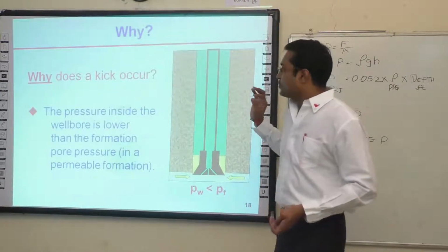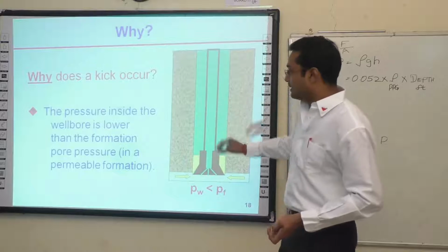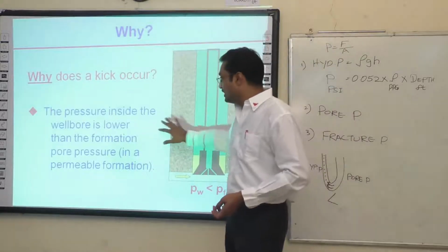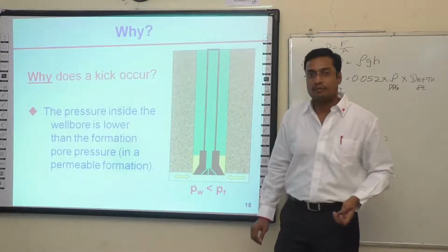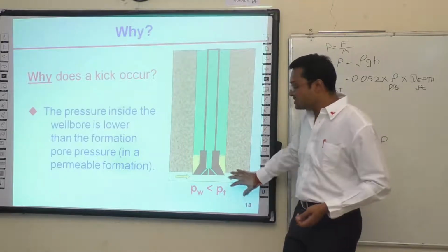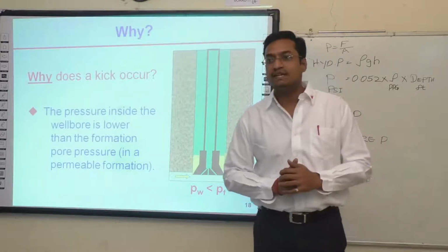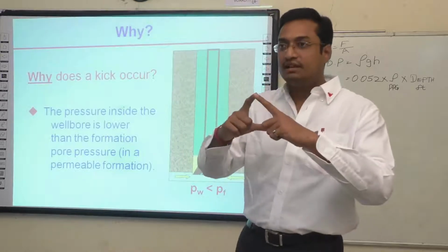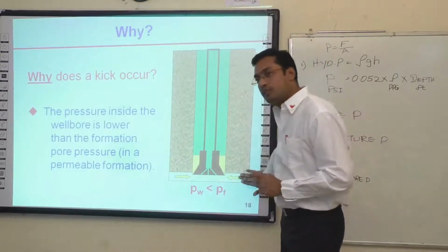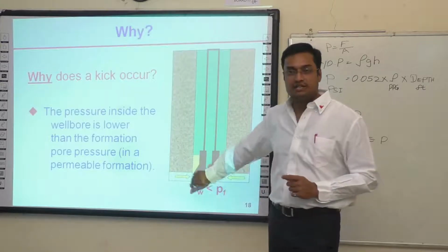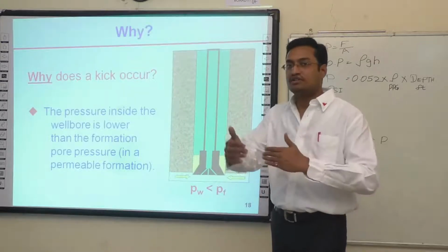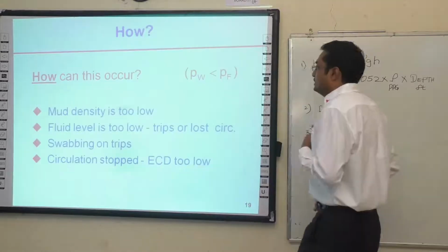And why does a kick happen? The pressure inside the wellbore is lower than the formation pore pressure in a permeable formation, because the intensity of the kick is decided by the difference in pressure and also the permeability of the formation. If the permeability is more, the intensity is more. So your reaction time should be quicker.